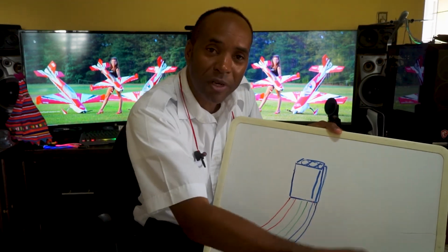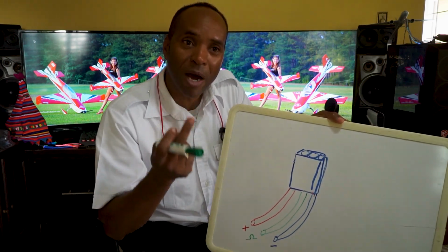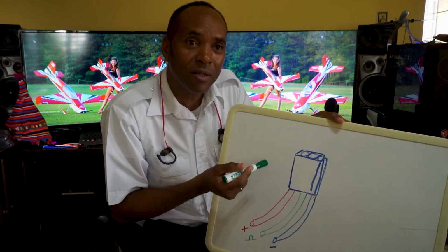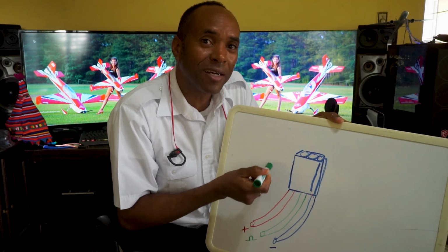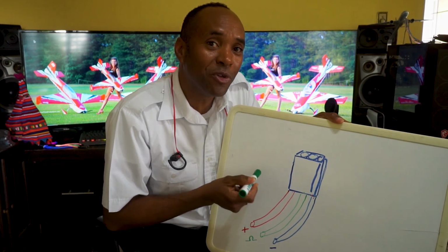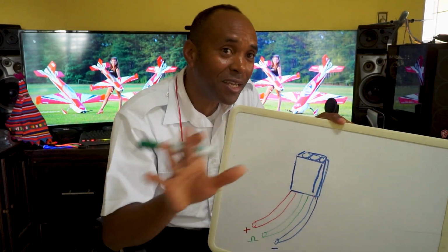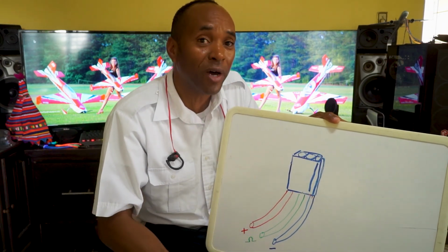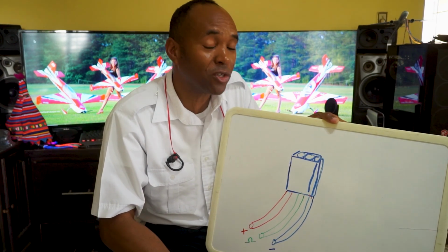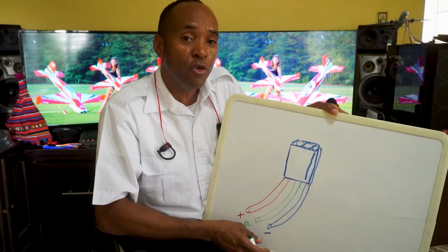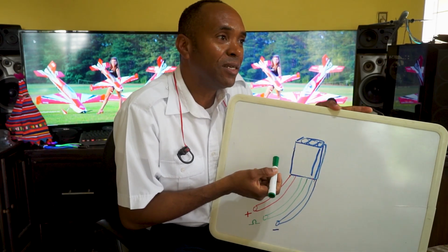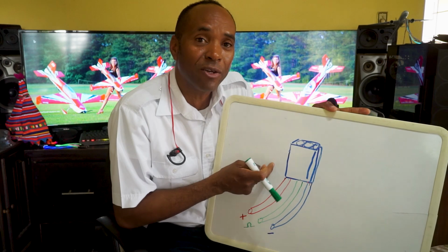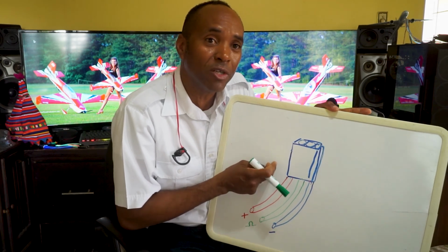So you see, when you add up everything, if you have one battery and it is going to exceed 7 or 8 amps continuous, this RC connector is going to get hot, it is going to melt and short circuit the thing, and you're going to have white smoke and fire, and your plane is going to crash. So if you know that your system is going to exceed the capability of the RC connector, you need to do something about this.